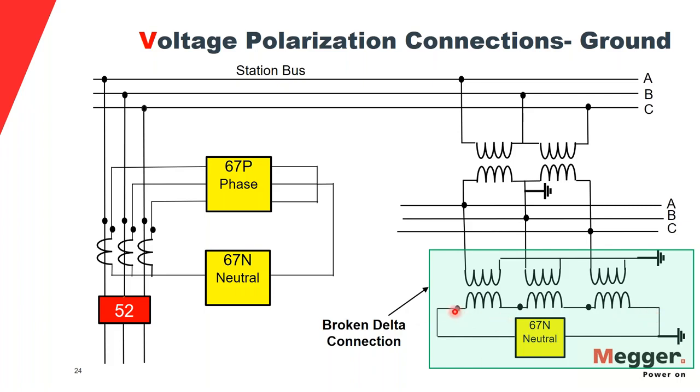So when you do this, this guy right here is computed from Kirchhoff's voltage law. You would see that it computes nothing but phase A voltage plus phase B voltage plus phase C voltage. So if you remember the symmetrical component theory, phase A voltage plus phase B voltage plus phase C voltage is what? It's 3 times zero sequence voltage, correct? So that's where we are measuring zero sequence voltage from in the world of electromechanical relays. Even microprocessor relays employ this concept, but we'll see later.